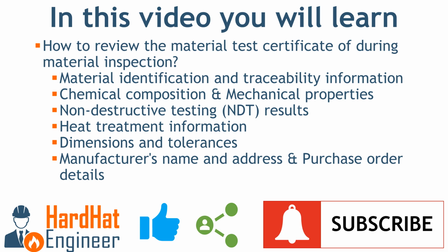Reviewing the MTC involves several steps, including material identification and traceability check, chemical composition analysis, assessment of mechanical properties, evaluation of non-destructive testing results, review of heat treatment information, examination of dimensions and tolerances, and consideration of non-technical information such as the manufacturer's name and address, purchase order number, and date. You will learn each of these in the video, so make sure to watch the video until the end.